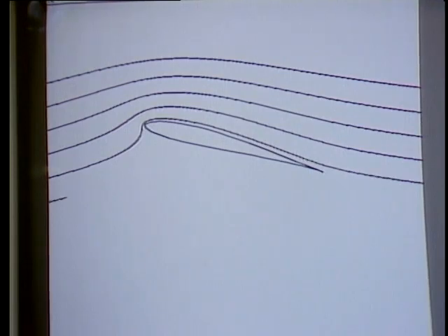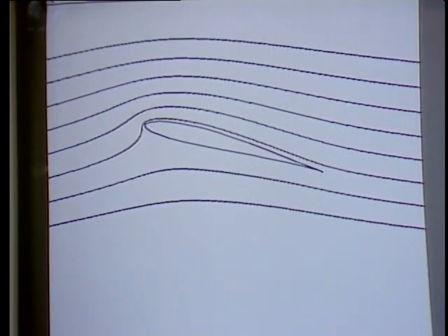Now, if we then take this and use a mathematical process called conformal mapping, we take the circle, we pull it and we stretch it, we pull all the streamlines and stretch them too in just the right way. We get something that looks like this. What we see is something that you probably recognize by now. It's our wing from the wind tunnel. Even though this is a very simplified vision of what goes into airfoil design, it is the starting point for some very sophisticated aerodynamic studies. Complex numbers are an invaluable part of that design work.